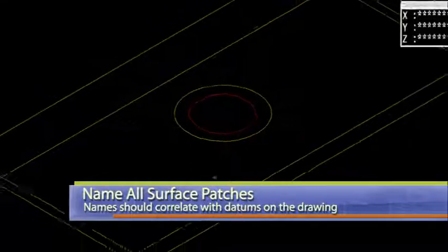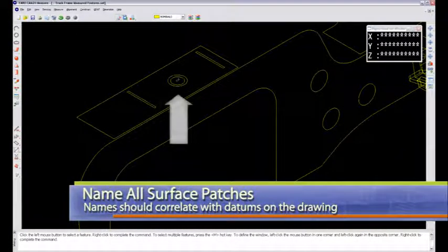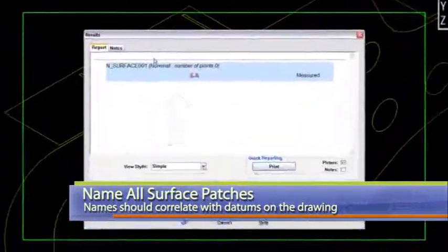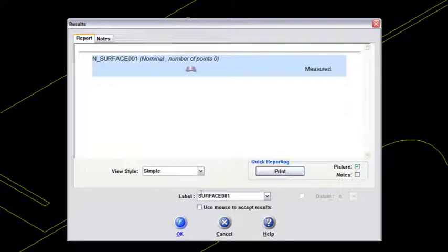Now I'll zoom out just a little bit and go to the other corner here. Same thing. I'm going to highlight that surface. Whoa, it only found one surface. I'll call that datum A2. Now let me take a look. If I hit enter, okay, it's highlighting that circle red. Let me now zoom out to the other corner. All right, this surface now, this little patch, I will highlight it. It only finds one. It's good to know. And I call that datum A3. I hit the enter key. There it is. It's turning it red.